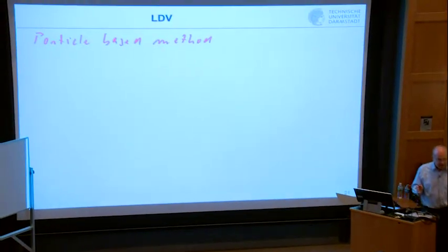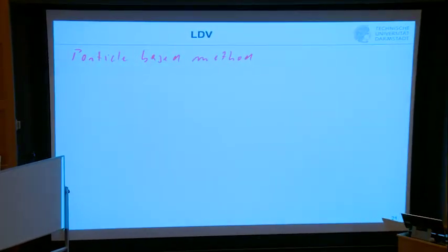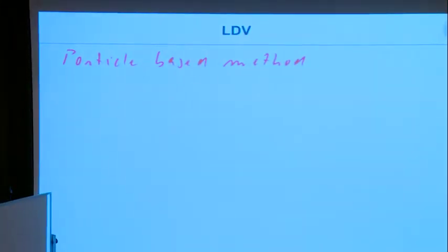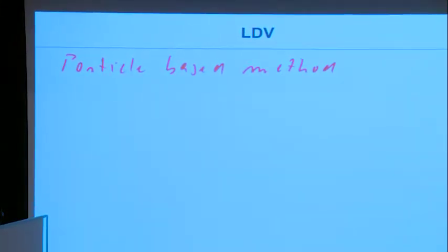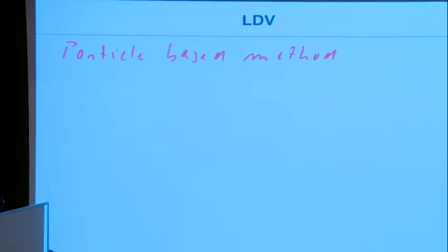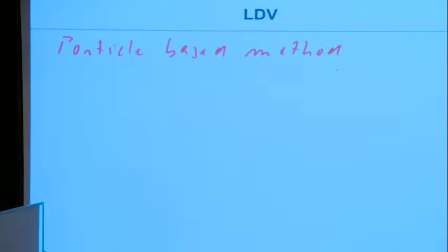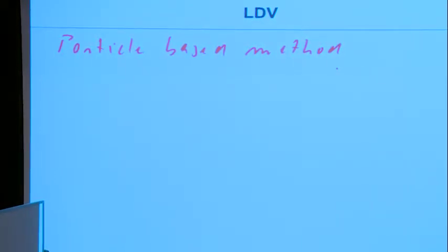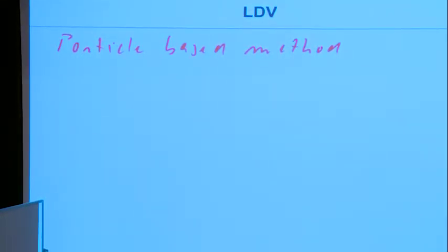And we have discussed that depending on whether you're only interested in isothermal flows, where oil droplets, aerosols are clearly beneficial or much better than chemically inert particles, those are solid particles for combustion applications. So the big problem here, or the big issue typically, is to select good particles and to bring them into the flow so that you have a constant seeding density.